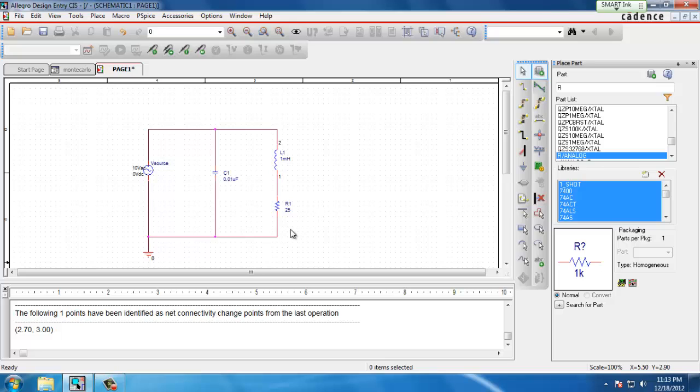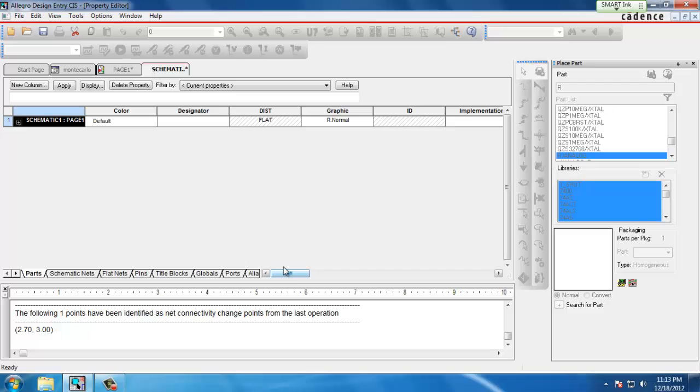And as we already described, the Monte Carlo analysis will rely on component tolerance. So here we will have to see where we can specify the component tolerance for our desired component. We'll choose the resistor R1, and to set the tolerance we'll double click the component, and then we'll see a set of parameters, and we'll scroll down until we find the tolerance column. So here in the tolerance column we'll choose our tolerance and we'll set it to 10% to start off with.